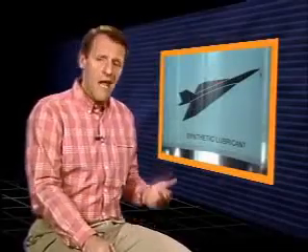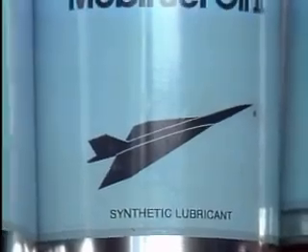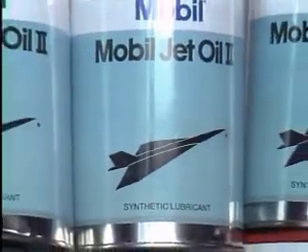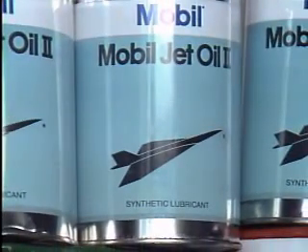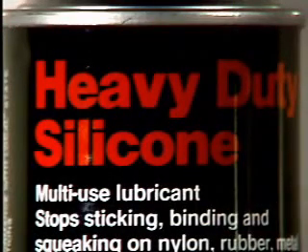Additives are able to make natural lubricants suitable for many different applications. But there are some extreme conditions where even additives aren't enough. For those conditions, many different types of synthetic lubricants have been developed. Synthetic lubricants are often made from substances found in petroleum and are designed to have the exact properties desired for specific operating conditions. One example of a synthetic lubricant is silicone grease.